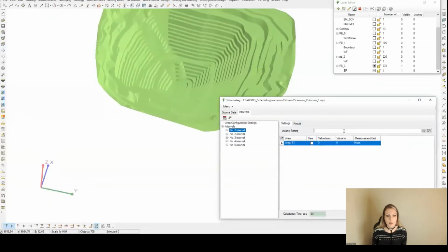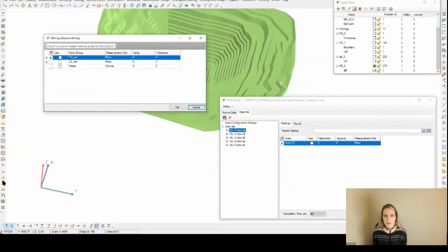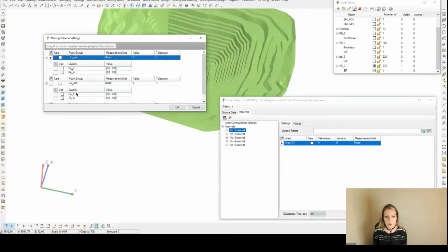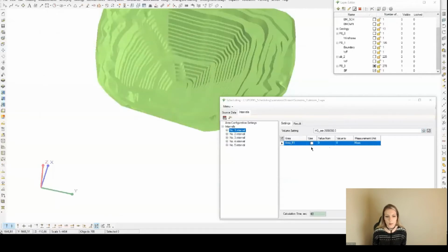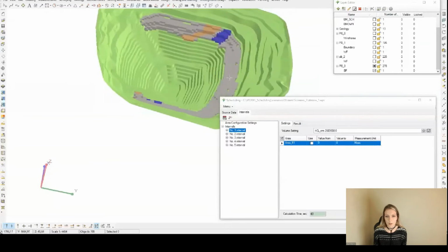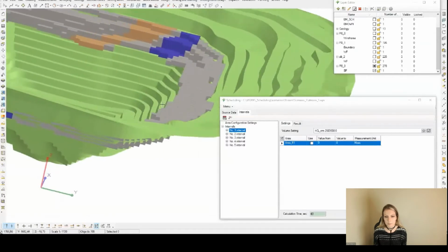So as target indicators for mineral, we use qualitative indicators, setting a range. And let's set the target indicator of 2 million tons for high-grade ore weight interval. The tolerance would be 200,000 tons at 10% level. With this initial data, the software will stop the search when the weight of high-grade ore reaches 1.8 million tons. So we click calculate and see the result.